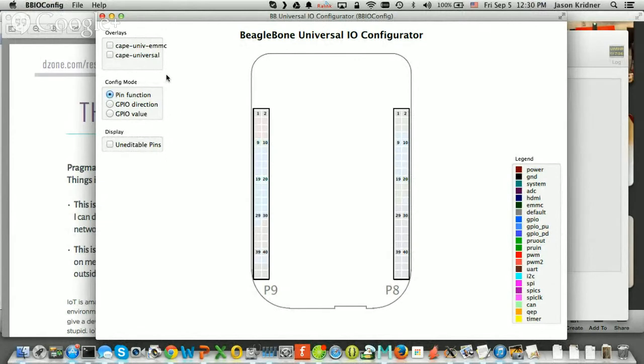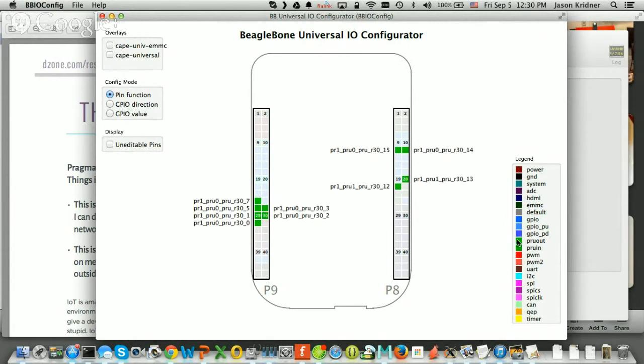So you have all these different pins, right? Only a certain number of the pins, like if I highlight these ones that say PRU out, those pins are directly accessible through the R30 register. So if you select that MUX mode on these pins, it would directly represent R30 bit 12, R30 bit 15. So if you see those numbers here,